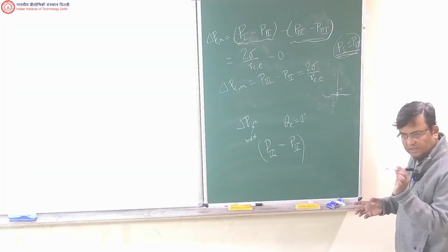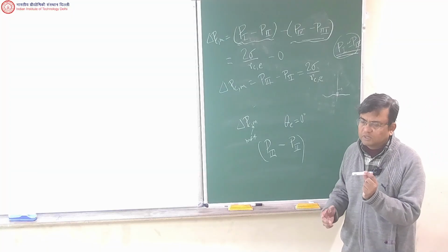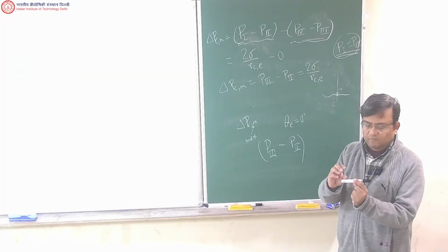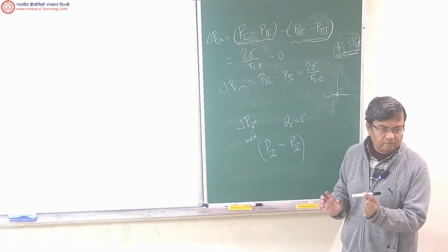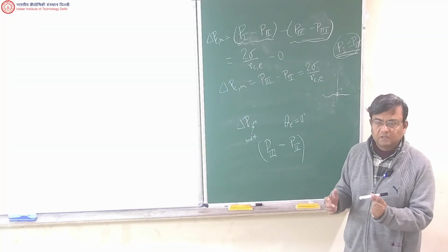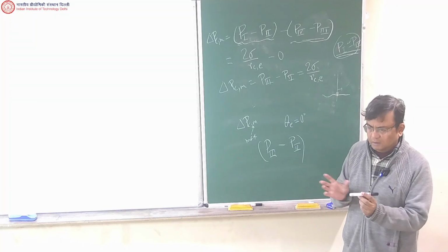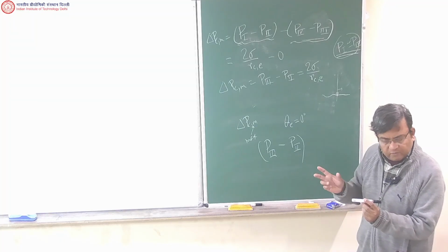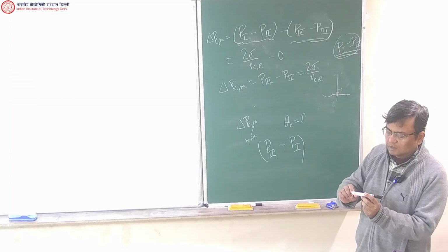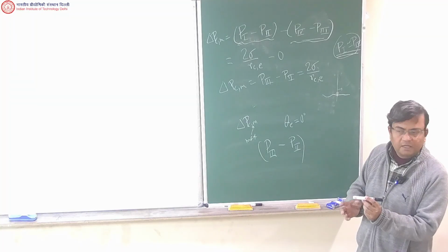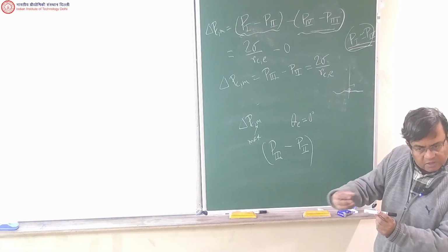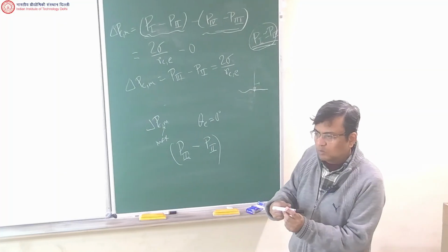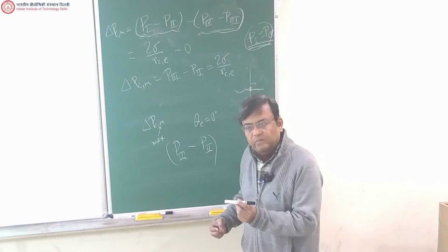Physically, that's what you should think: I've got an evaporator, I've got a condenser, I can generate a delta P, but is that going to be enough? This is one way of thinking. The other is that not everything is just pressure drop. It can also be the evaporator running dry, boiling happening here, or the sonic limit being reached because you're generating too much vapor, giving a very high vapor velocity.